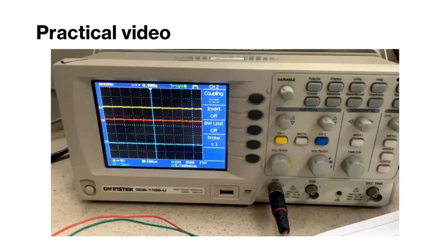Now, I didn't talk about demodulated and modulated output. So let's see what is demodulated and modulated output. Modulated output will help us to measure the linearity range of the LVDT. As modulated output is the VRMS, that is root mean square, we won't get to know about the displacement of the core, whether it is positive or negative.